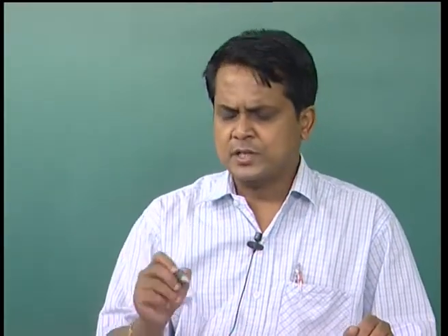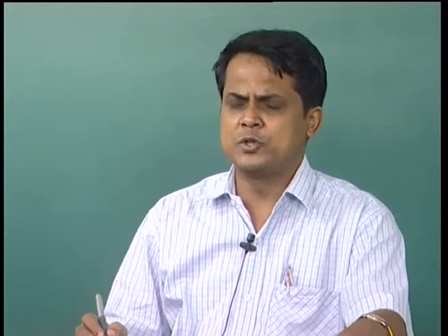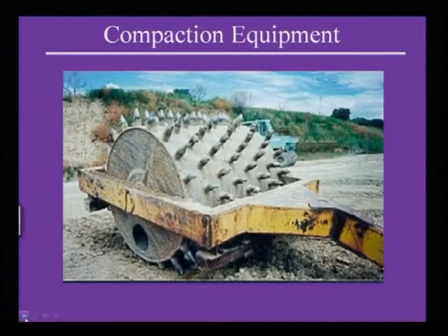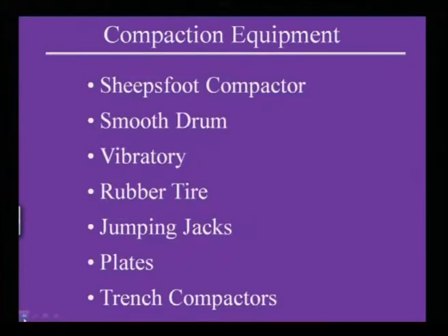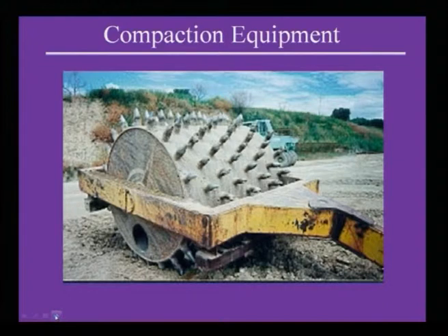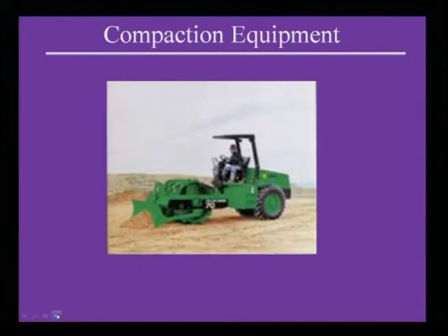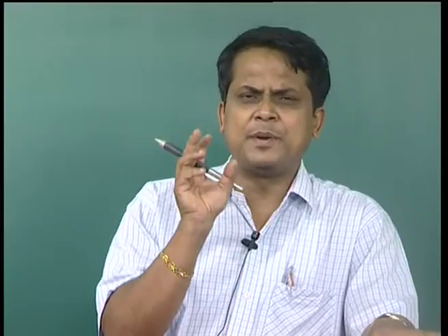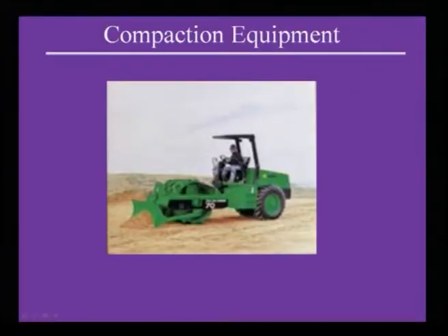Particularly for clay soils, sheep foot rollers are generally used. This is a case of sheep foot rollers. Sheep foot compactor; smooth drum, I say, for road construction and bitumens; vibratory for loose sands; and this is for cohesive soils. This is one case of sheep foot, and then again another sheep foot. There may be denting above this, it may be a triangular denting or maybe a square shape.